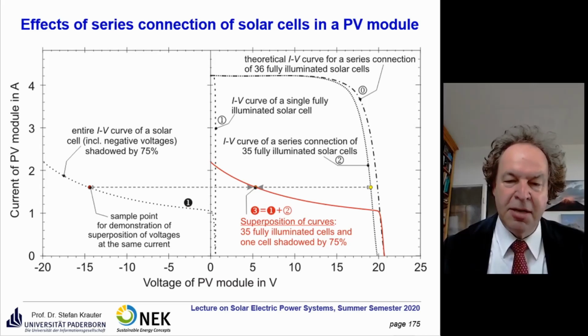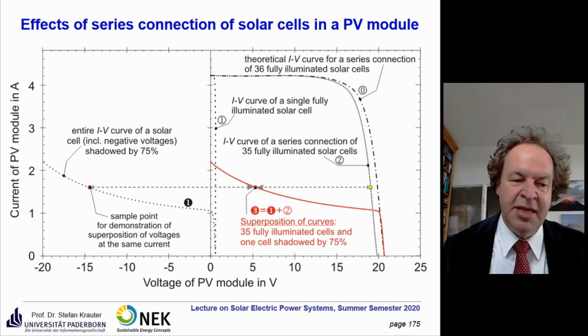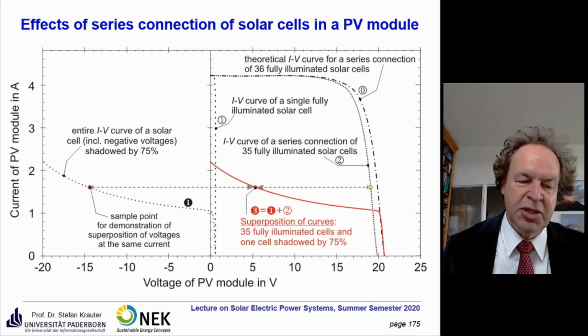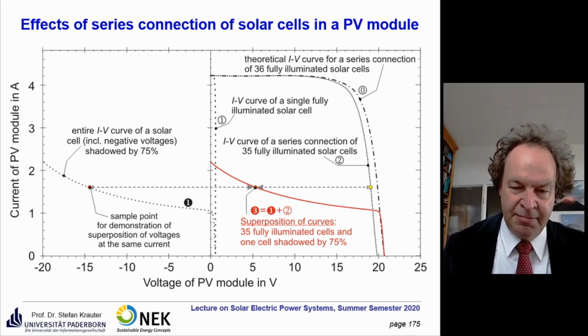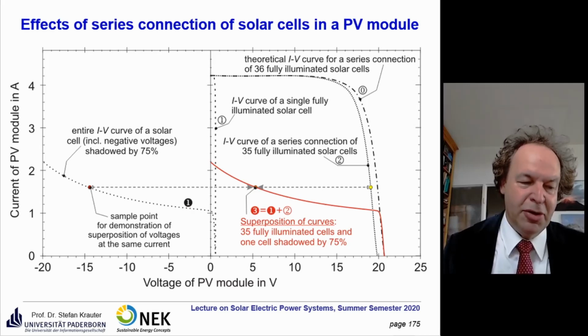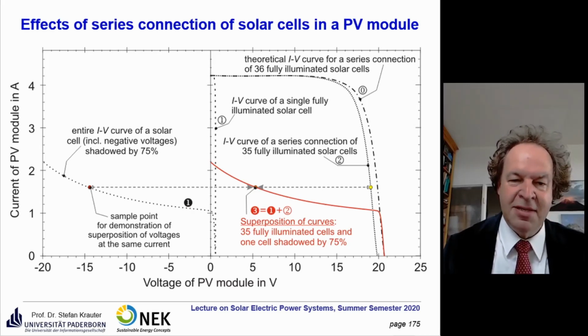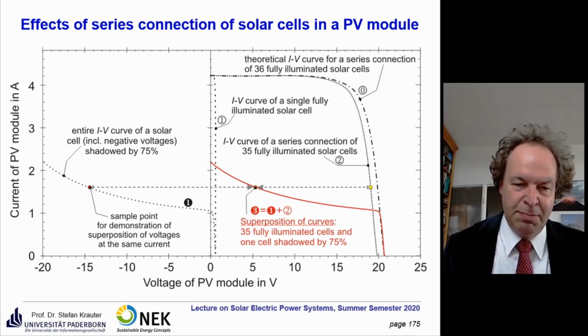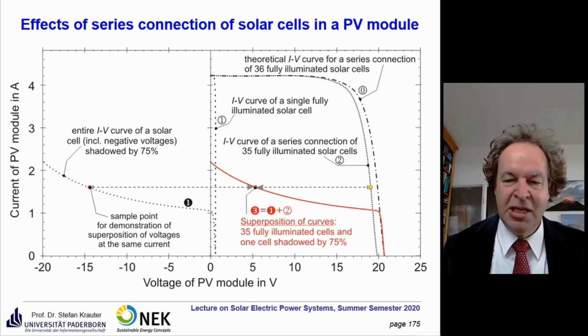It starts at a single point, it's called a hotspot, and then all the current goes through that one. So there starts a current flow, but while this point is very small, it starts to increase and is destroying that cell. The performance is then better because this cell is bypassed due to the hotspot, but you don't want your modules being permanently destroyed.